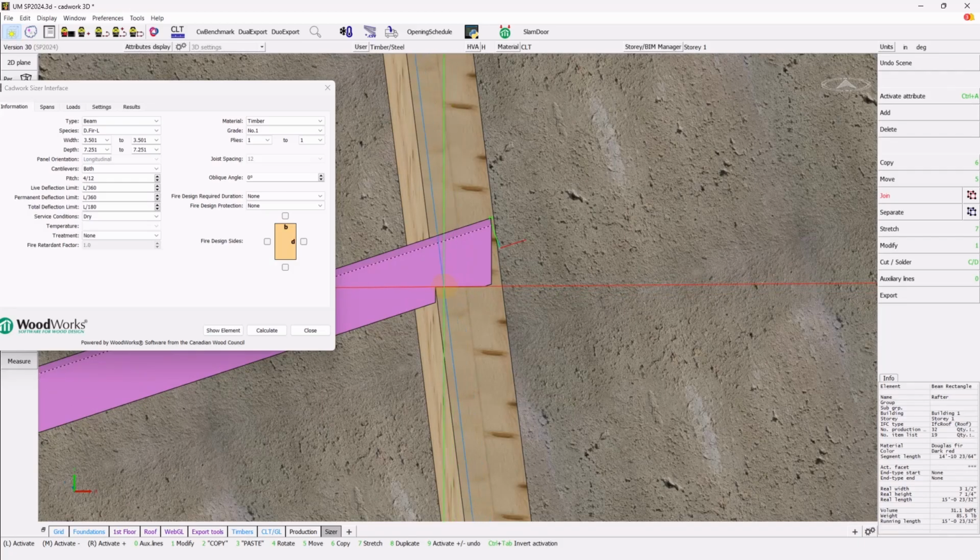So the support is actually the center of the support, and so between the center, if you project, if you ignore the slope, the midpoint of the bearing surface and the tip, there is a distance, so that's considered as a cantilever.